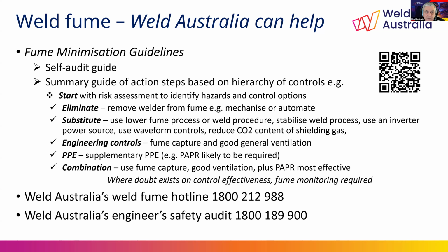Now, this document also contains a lot of useful material and advice, which I have very briefly summarized on this slide. Now, as I've said, there is no one-size-fits-all approach to fume control. Every fabrication shop is unique to the type of work and layout that they perform. Now, regulators do promote fume capture via a variety of methods, but not all methods are equal in all cases. On-gun extraction should be considered given the improved technologies currently available, but may not be suitable or effective when welding out of position or where access is limited.